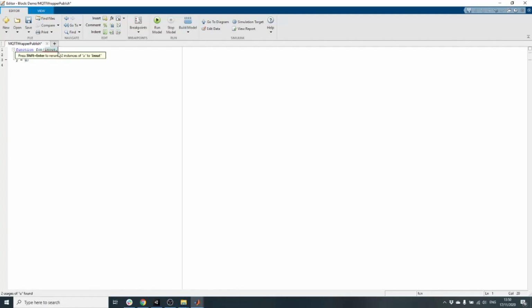We take a value, an input that can be published on a particular broker. Then we write the topic that it can publish on. We have the address, the client ID, the port, and the QoS. And we can end this function here.